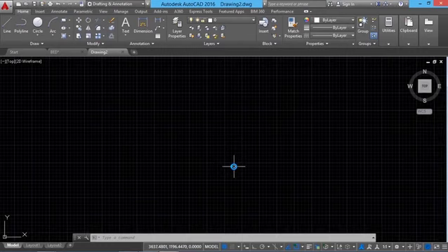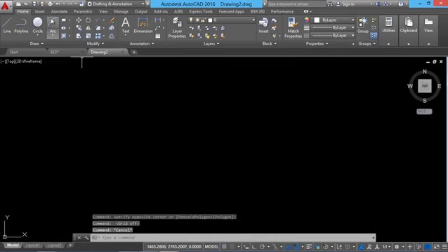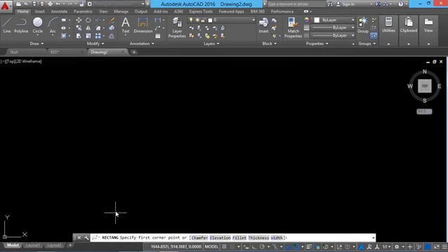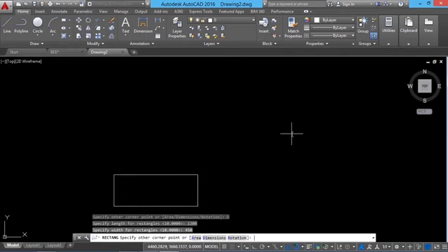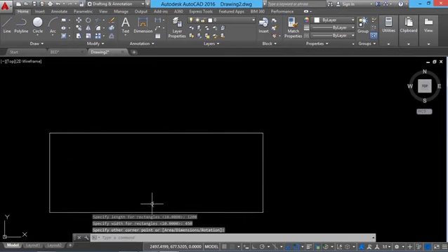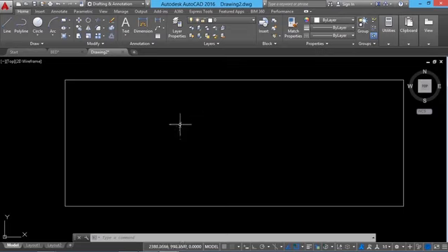and I'll create a room with a dimension of 1200 by 450 centimeters. So I'll go to rectangle, I'll click the first corner here, then go to dimension option and I'll give a length of 1200 and a width of 450. And I'll click to define the opposite corner point and let this profile indicate the inner dimensions of the wall layout of a hostel room.